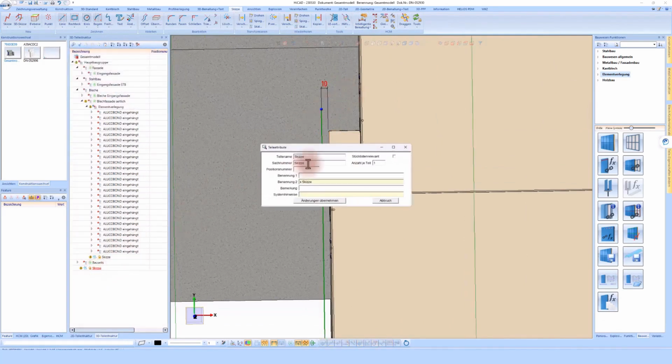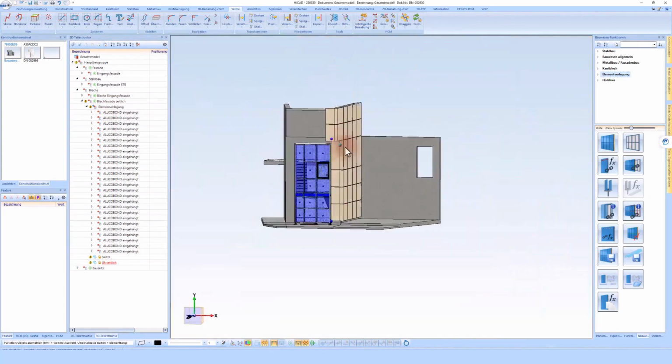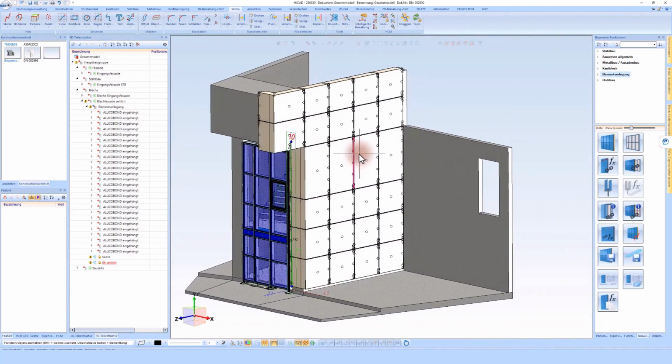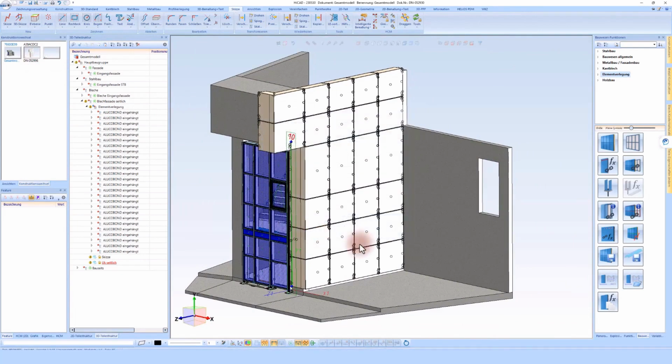Of course, I can also name this sketch so that I can be more familiar with it afterwards. I pull this sketch back into the element layout and have created my substructure for this area in this case. I am switching back now to show it, and because it is also easier to work in small constructions, to the small construction.